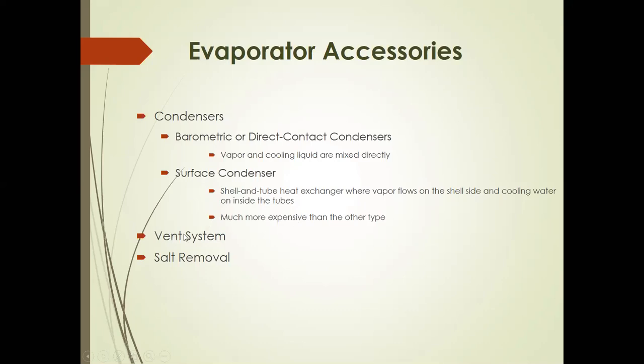Another accessory that is being used is the vent system. These vent systems are used when, in the process of evaporation, non-condensables are forming. These non-condensables later on will impede heat transfer, so there is a need for them to be vented out. The vent system is responsible for this.